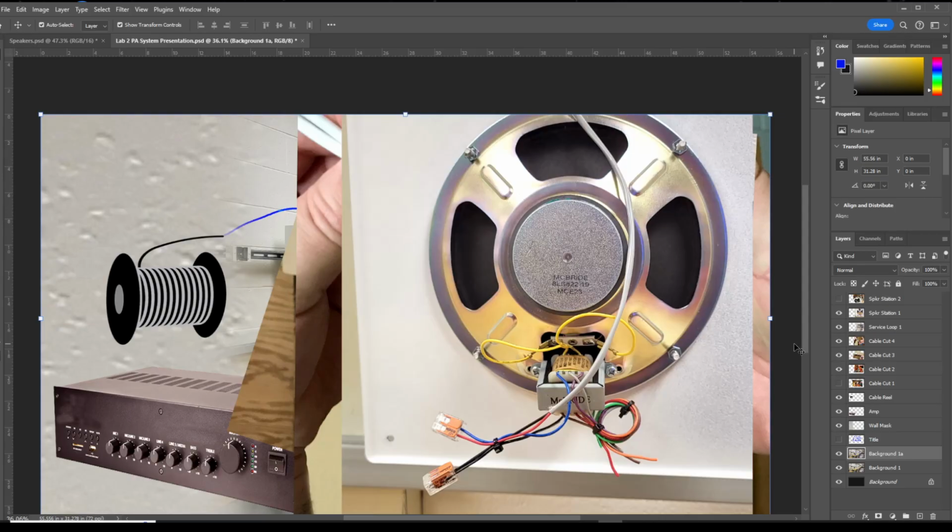Now, at the speaker station, when you pull the wire out through the back of the speaker baffle, because it has to be through the back, because eventually the point is to put that face plate baffle onto the box. So here's the wire that runs from the back of the box, and over here we use those Wago connectors. You can use them, or you can use the wire nuts or the twist-on connectors, whichever way you prefer.